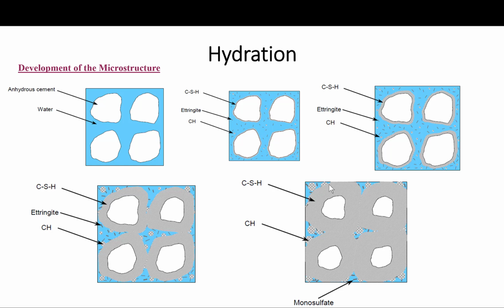However, what is presented here is the widely accepted theories, and it is based on SEM, scanning electron microscopy, observation, and the help of other techniques such as the heat of hydration, calorimetry, and others. This approach, though, still assumes that the hydration is uniform around the cement grain, despite some evidence to the contrary.